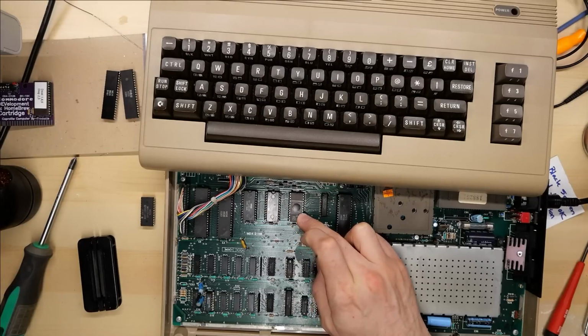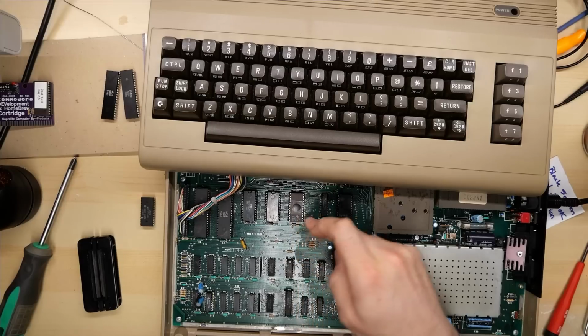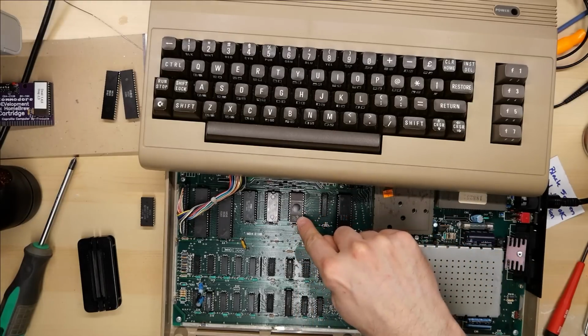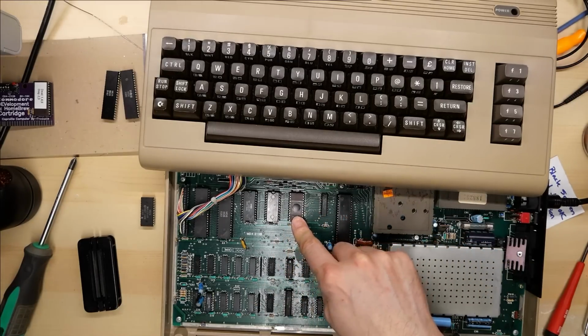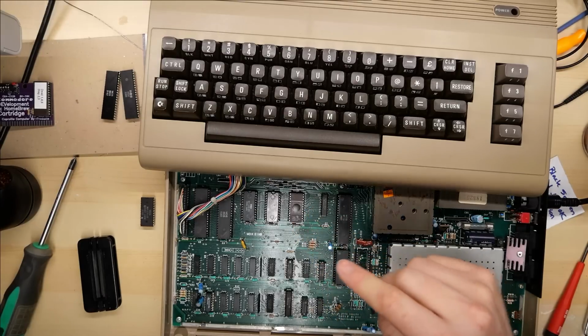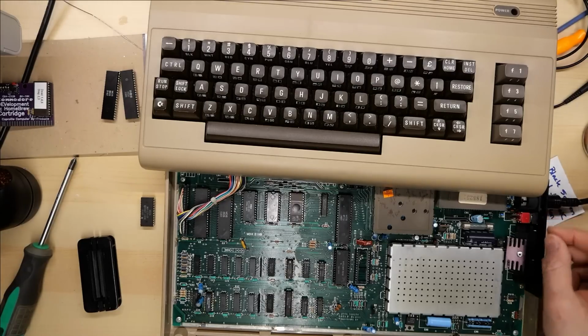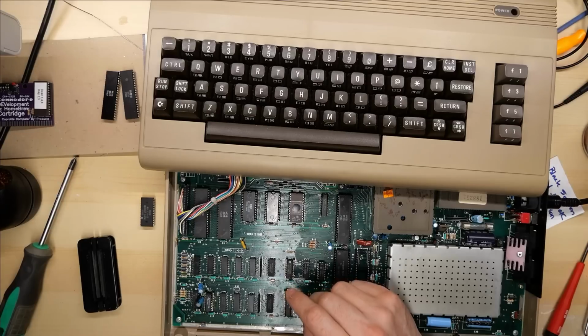You can't just stick the ROM chip from the VIC-20 into the 64. That doesn't work, and that's because the chip that Commodore uses is slightly different on the VIC-20. In fact, you can't even use this chip in a VIC-20 either. I think it's because the VIC-20 has extra chip select lines that the 64 doesn't have. The 64 can work just with a standard EEPROM. So let's see what happens if I turn this on now. Will it have fixed the problem with those characters?